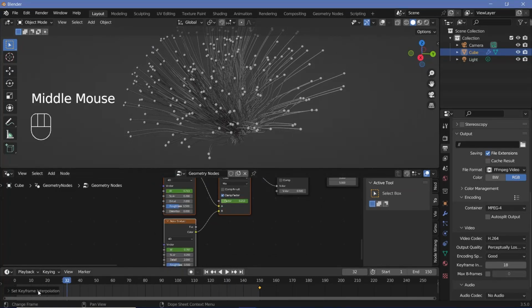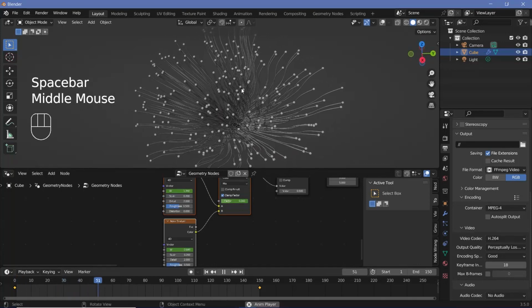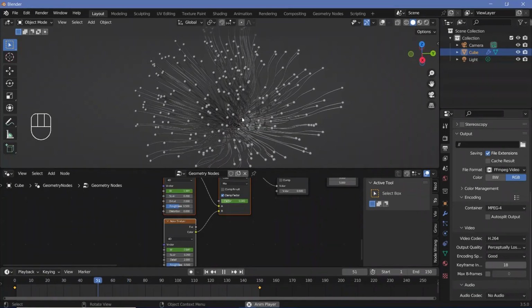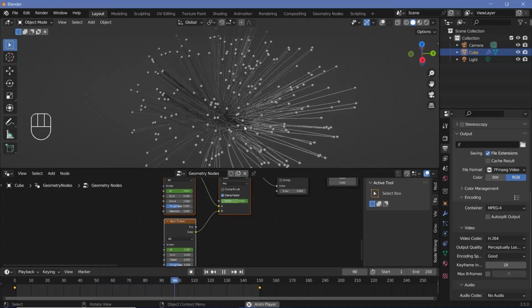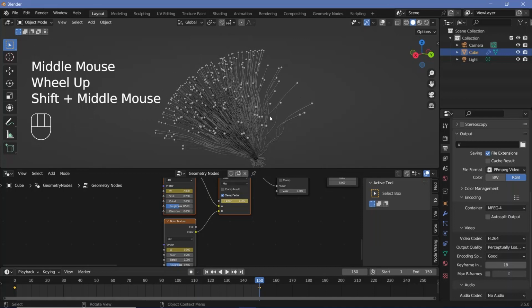Of course, if you want to exaggerate this motion, you always can by changing this from -1 to maybe something like -4 and pressing I, and then going to frame 150, changing this one to 4, and then pressing I. And that way, the motion is going to be far more exaggerated. So all of that is up to you, but I'm going to keep it as a fairly subtle motion at -2 and 2.